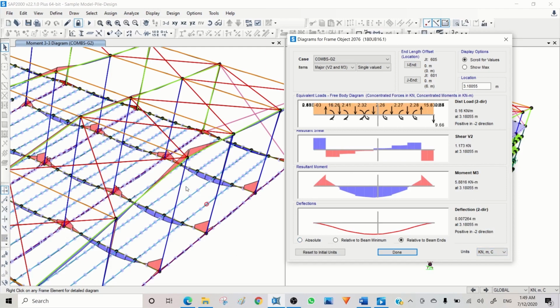As I said, when you mesh the slab and beam together, these elements are acting together as an integrated structural system, and a slab stiffness will be mobilized when the beam deflects more than the slab, so the slab directly transferring loads to the columns. But we need to see how much that difference will be. The moment definitely is not correct. The deflection, we need to see how we can see that. We need to model a composite beam here.